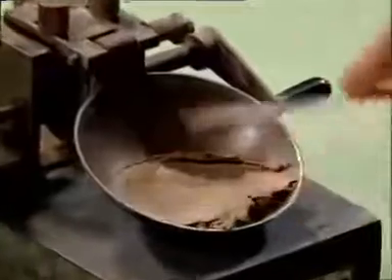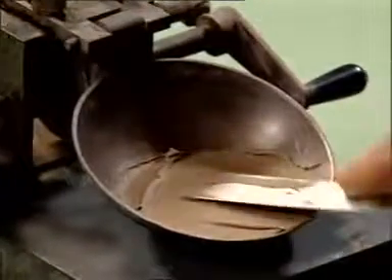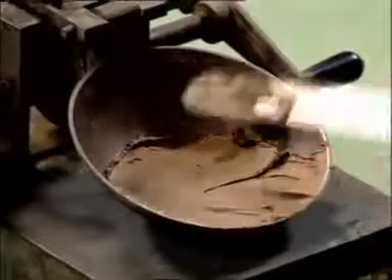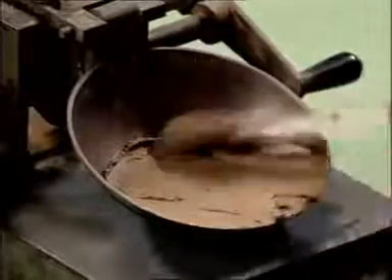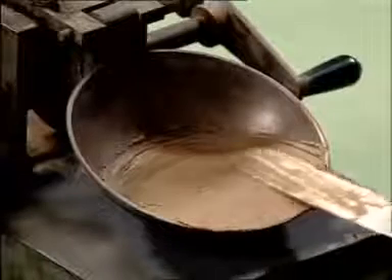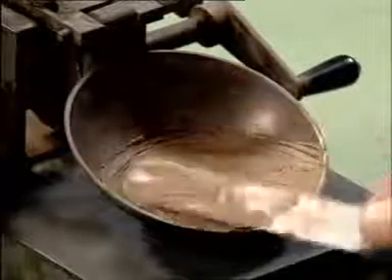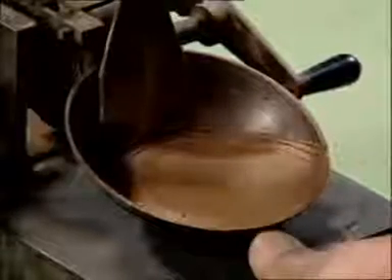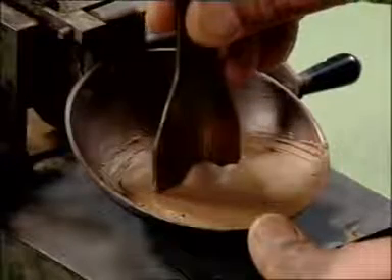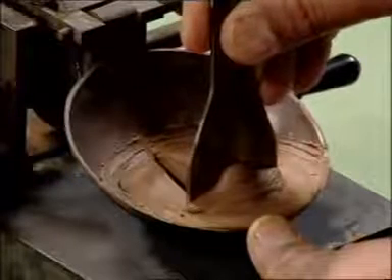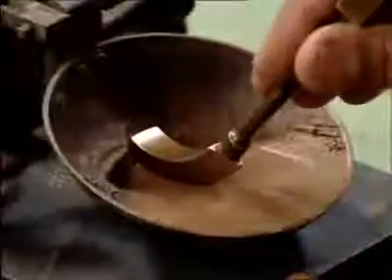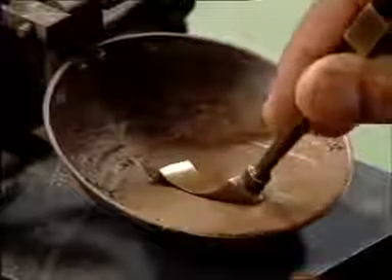Now, place a portion of the paste in the cup of the liquid limit device. Squeeze down and spread the paste in the cup with the spatula. Trim the soil at the top so that the maximum depth of soil in the cup is 1 centimeter. Transfer the excess soil to the dish. As the soil is clayey, use Casagrande's grooving tool to divide the soil paste in the cup into two halves in a direction perpendicular to the axis of rotation of the handle. If the soil is sandy, use ASTM type grooving tool.